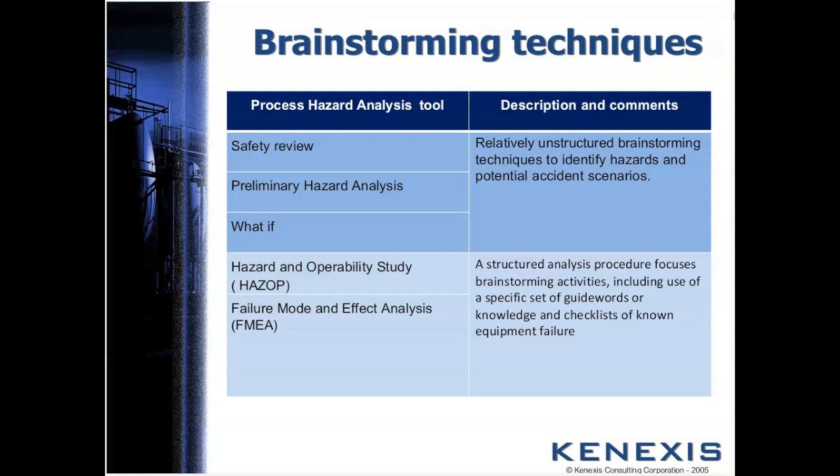Preliminary hazard analysis. In fact, I conducted a preliminary hazard analysis a couple of weeks ago. The PHA focuses in a general way on hazardous materials in the major process areas of a plant, and it's conducted early in the development of a process where there's not as much information on design details or